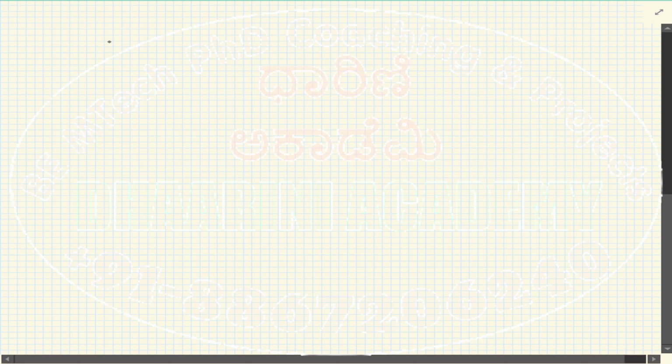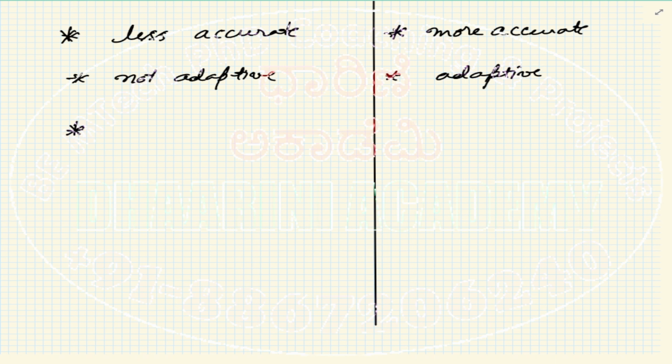Then, how good is a system which is sensitive to disturbance? Which one is more sensitive to the disturbance, and which one can control the disturbance? The open loop is sensitive to the disturbance because there is no control. A disturbance is an external, additional input. If that gets added to your input signal, the system will take it as an input itself, process it and give an output. There is no control over it.